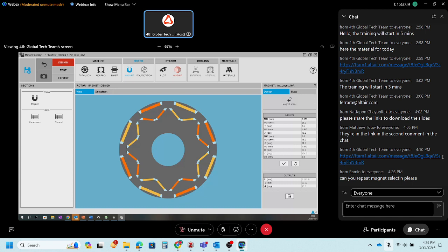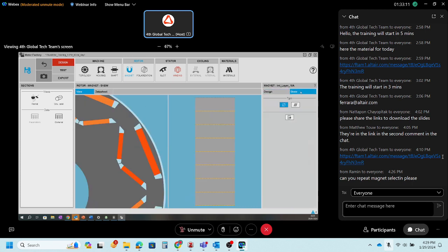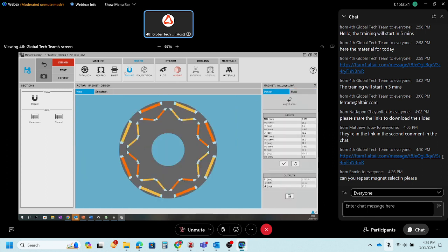In this case, there is no skew on the rotor for this motor. If needed, a continuous skew can be defined through the skew tab. This is the continuous skew, and the skew angle can be defined either by slot pole pitch ratio or as shift angle. It depends on your needs.